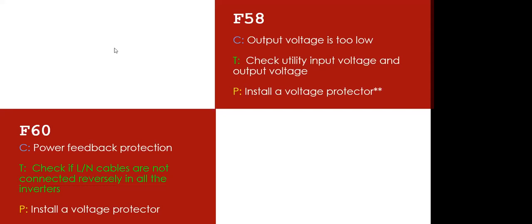In that case, we need to check program 28, where maybe we connect in parallel, then we want to use the split method. We want to use 1 inverter per phase or 3 inverters per phase, and we want to achieve 3 phase. So we need to check program 28, then program 9, so that we can set our output very well.